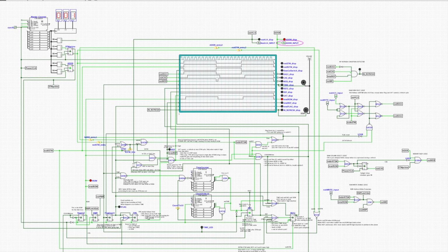Same for the counter increment. It has its own set of flip-flops here that are all imbricated into each other, and they wait for some of this and for some of that. It's just a miracle that this works, actually. And then something I didn't quite understand either is that there are two different refresh mechanisms that lead to two completely different timings. There is a refresh when the memory is accessed. Right now, it's a RAM access, and it relies on all those flip-flops.